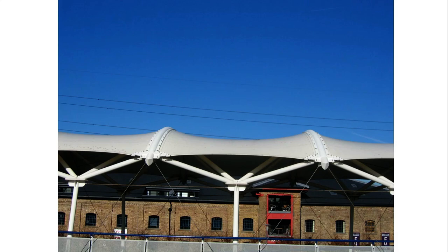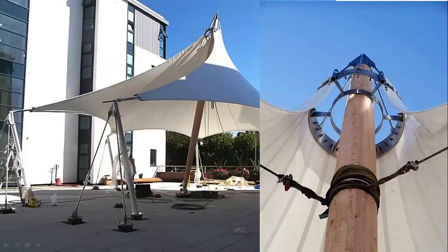Arch supported, you can do the same thing. So here's a steel arch supporting the membrane. It's worth, as I said, looking at the detailing of these because you're pulling on fabric. Now you can see quite clearly here probably that there's steel wire running through, and then it's gripped at the end, and then there's another detail here, and of course you don't want to pierce the fabric at the top, do you? So here's a lovely little stainless steel ring, two rings actually, one bolted on the inside and one bolted on the other side, locking the fabric together, and then that ring is held in tension to the top of this rather beautiful timber mast, doesn't it?